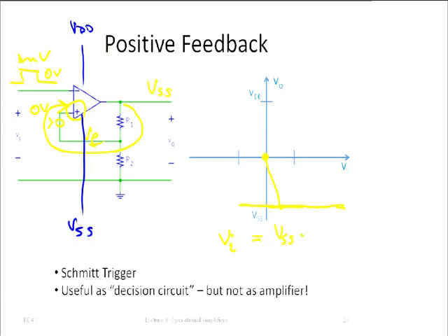When Vi is equal to Vf, and Vf is going to be VSS times R2 over R1 plus R2, right? When the output voltage is at VSS, then Vf has the value VSS times whatever that voltage divider makes it to be. So at some point, at this voltage here, they're going to be equal. And then if I make Vi just a little bit more negative...